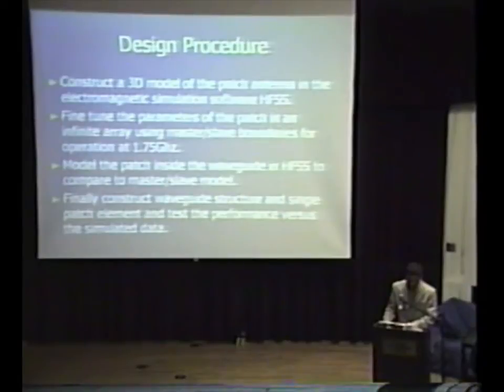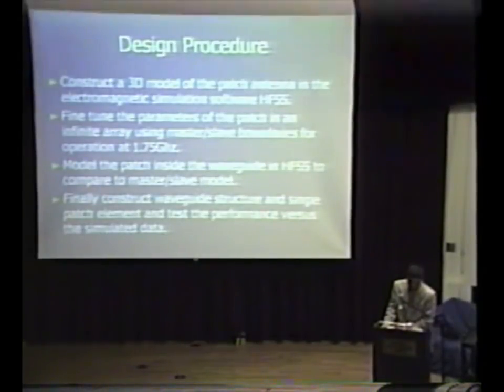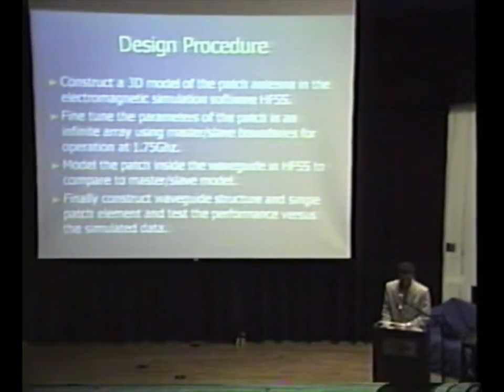The design procedure: first, I constructed a 3D model of the patch antenna in the electromagnetic simulation software HFSS. I fine-tuned the parameters, first using the infinite array boundaries at 1.75. I used these parameters and then created the waveguide model in HFSS to compare to the infinite array model. Then finally I constructed the actual waveguide structure and single patch element and tested the performance versus simulated data.